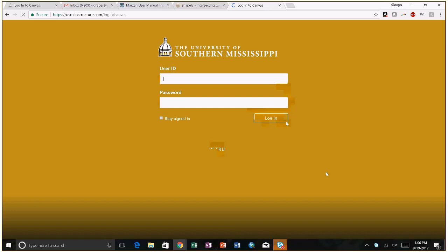They're getting more and more capabilities. Even the consumer models now have sensors. They can detect buildings. They can detect movement. But really, if you only have a GPS location to go with, and that GPS location is bad, that's why these kinds of things happen. Some people call it flyaway. It all of a sudden started flying away. Well, it wasn't that it was flying away. It actually thought that its position was changing, and it needed to stay where it was.